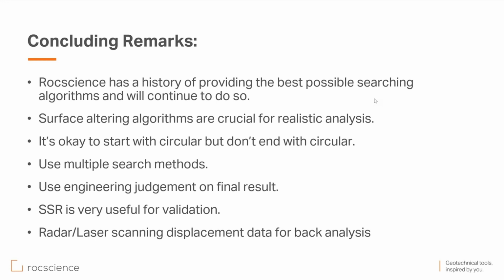Check your input. I can't tell you how many times I did technical support and somebody sent a model and said, I added water, but the factors of safety are the same. And you look and you see, okay, well, the water wasn't properly applied to a particular material. And if you look at the pore pressure on the actual failure surface, you'll quickly see that it's 0. And then obviously you didn't properly apply it and you can go back.